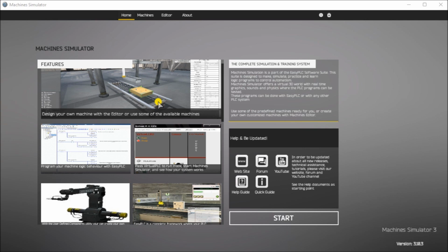Pallets are loaded and unloaded into the stacker machine. A maximum of 30 pallets can be stored. The stacker will work as a FIFO, meaning first in, first out device. This means that pallets are stored in a sequence and retrieved in a sequence. The Click PLC will be used to program this virtual 3D stacker machine. Indirect addressing, or pointers, will be used to track positions on the stacker, to store and retrieve the pallets.